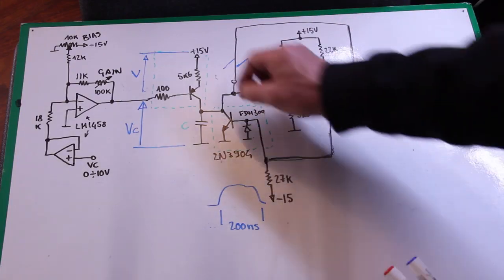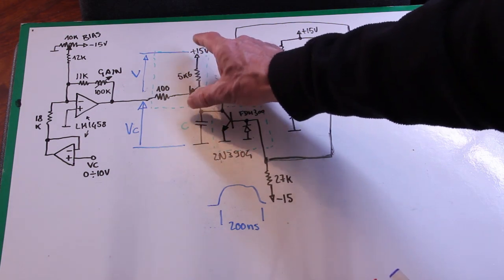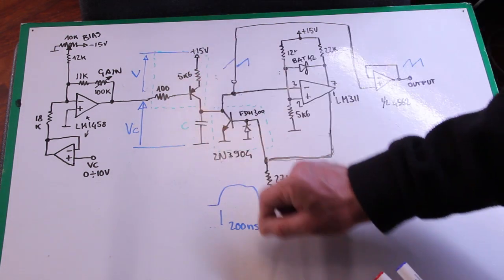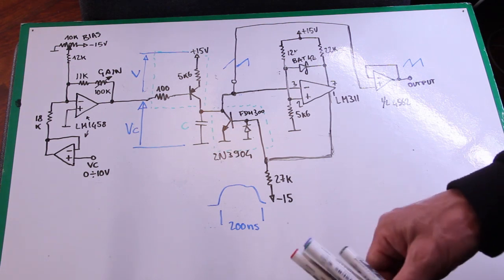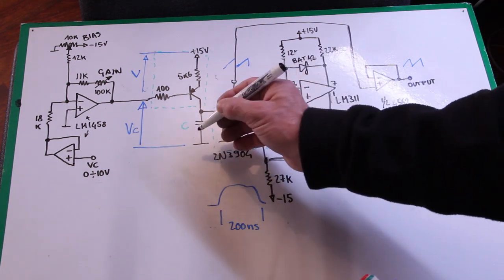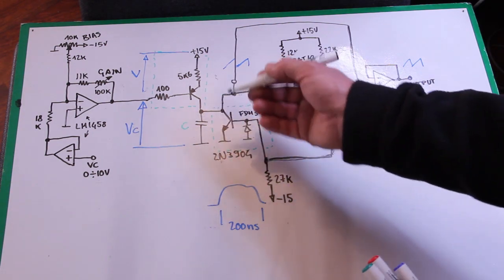So the idea is a compromise, using smaller capacitors, say less than 100 nanofarad, and to expand the range of frequencies for the same capacitor. So what we have to do is allow this range to be a little bit larger and use capacitors here that are below 100 nanofarads, that is the limit.